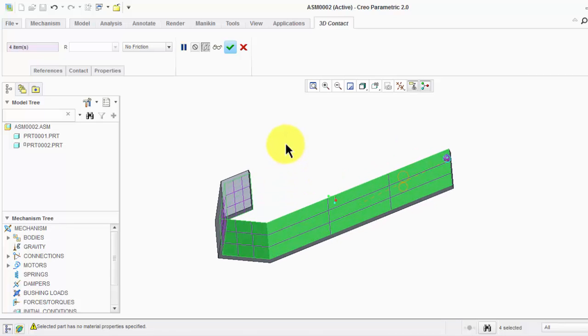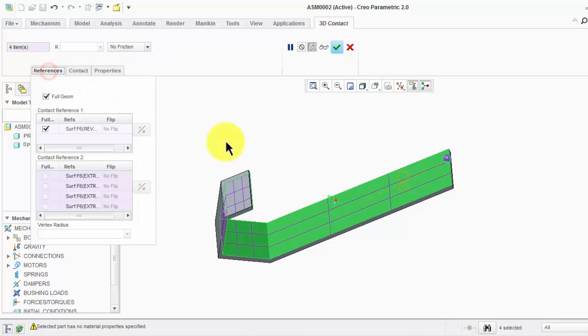Okay, so here the main parameter which controls the sliding or the rolling is the value of the friction coefficient. So in this case you have two options here. The first one is to define the friction coefficient values manually, or the second one is to define a material for each and every one, and then you will make an actual simulation with an actual material.